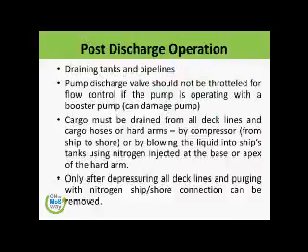Now, once we are completing the discharge, we are stripping down. What we will do, we will drain all the lines and tanks, and we have a big responsibility of now maintaining the temperature of the tank, because now we have discharged almost all the cargo. So pump discharge valve should not be throttled for flow control. This is the very, very important thing, that you should never throttle the pump discharge valve.